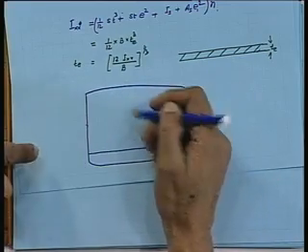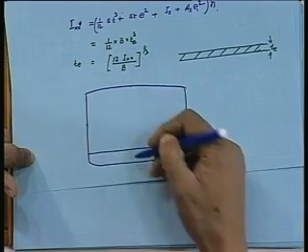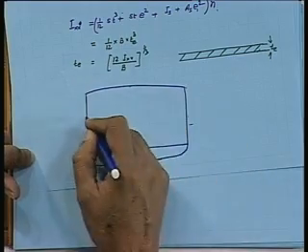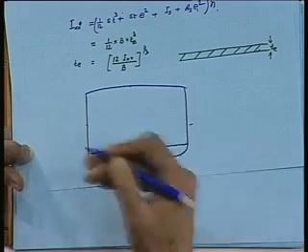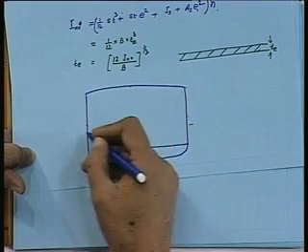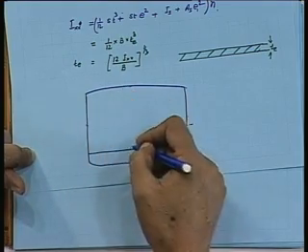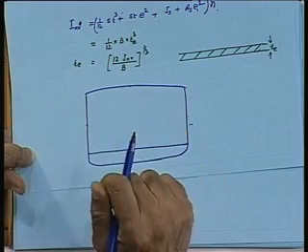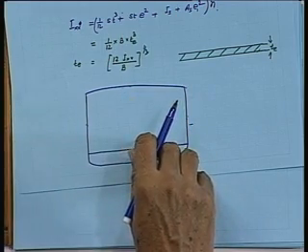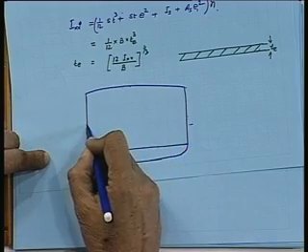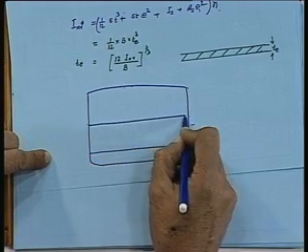Now, the same thing applies if this span is also more. If you have a second deck trying to cut this span. If you do not have a second deck, and consider this clear depth is about, say, 10 meters, then once again you are going to have a very deep stiffener, and to cut the stiffener, what is normally done is you put a stringer here.